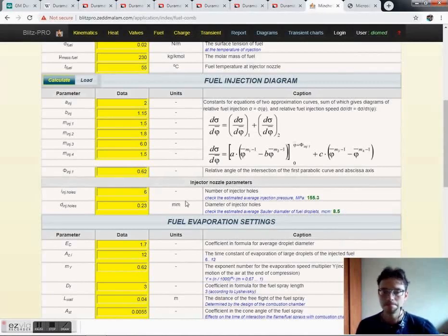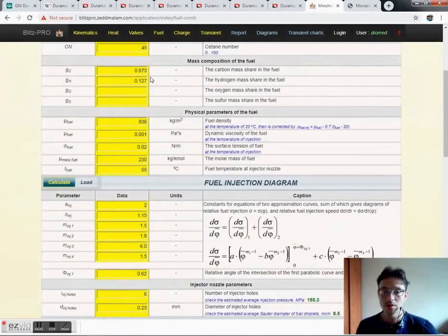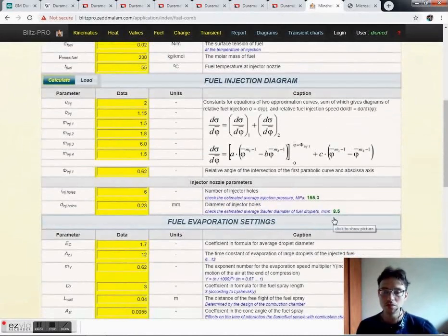So we can see that using this combination we can match these. But we know that the LML engine has an 8-hole fuel injector, and yes, it has. So if we use 8 holes, we should make the bores smaller, just to keep the pressure at the needed level.